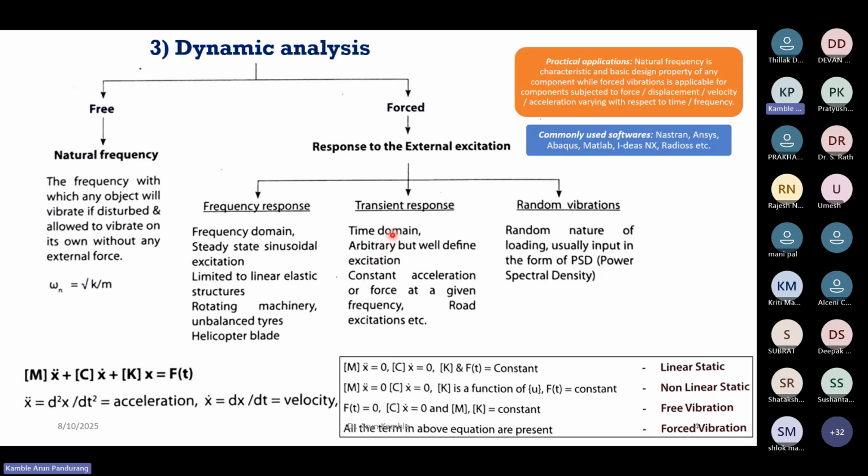And the second one is the transient response. This response we find in the time domain, and we use arbitrary but well-defined excitations and a constant acceleration or force at a given frequency. For example, in case of road excitations, we can use this type of analysis.